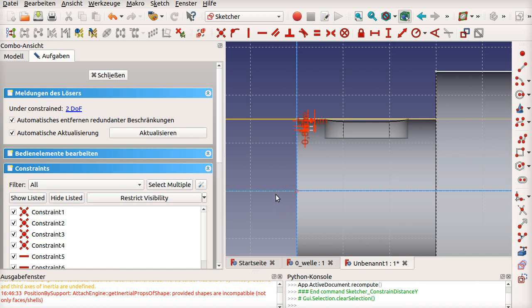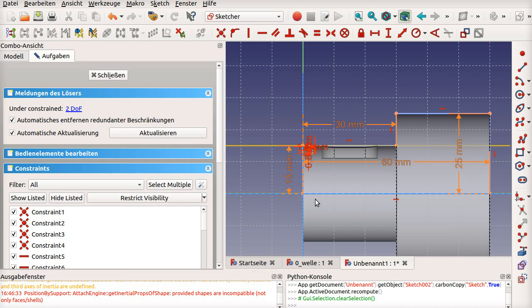We can't measure to the center because then it won't follow. So we need to measure against our sketch we already have. Therefore FreeCAD has a good ability here. Just turn on the behavior, here the blue lines, and here's a button that says copy of geometry. So I select that one here, and all the measurements from the first sketch come into view.